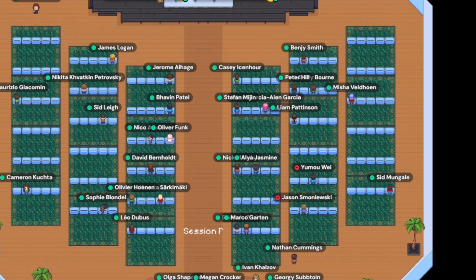That's one of the things that Mahmoud was looking at, really making sure that, for example, the surface mesh that you might use directly corresponds to the volumetric mesh that you're using in MOOSE. So he did some convergence studies here, making sure that, as you refine the meshes, they all still correspond well to each other and limit drastically the amount of errors that you introduce because of the differences in mesh.